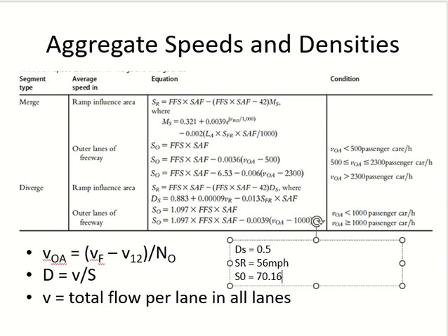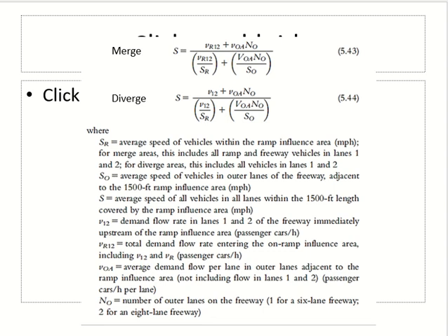It shows that these equations are not for level of service F. Okay, they are not giving accurate answers. That's why they give us a check that you should stop there. Because if you continue, the equations will give you some answers, right? They will give you density, they will give you speed, but they are not supposed to work after level of service F. So that's why they gave us the check that when you don't satisfy the check, you stop there. Level of service F is there. Don't go there. Okay, they know that the equations are not good.